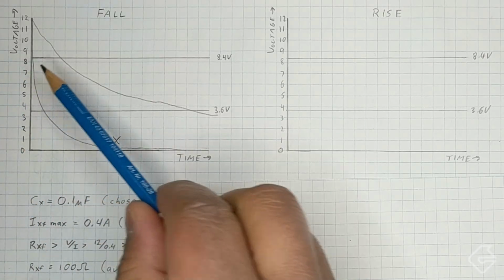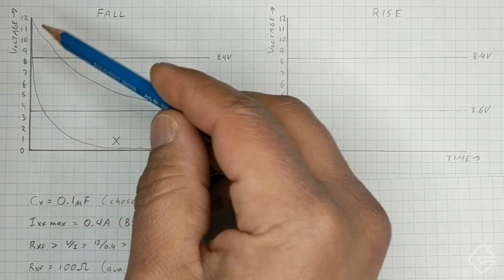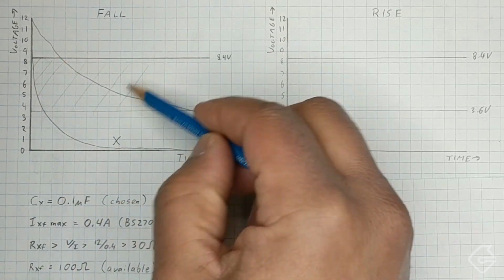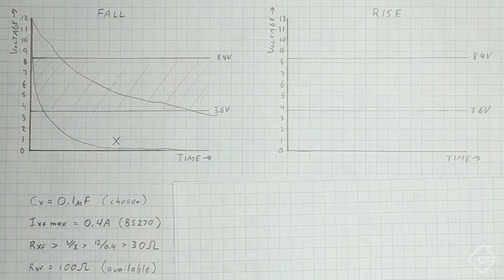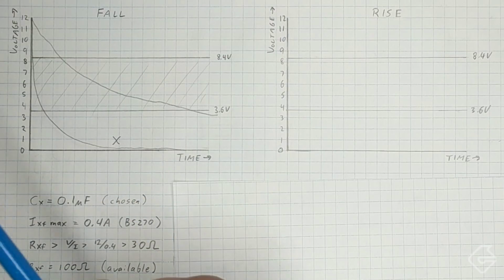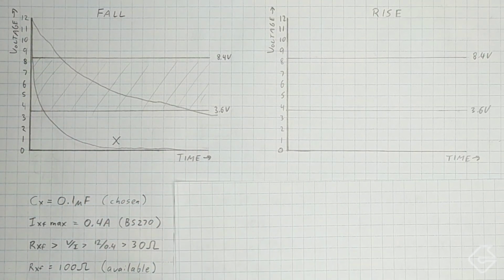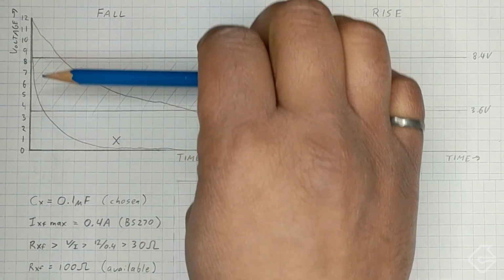And so this area in between, I'm going to call the danger zone. We do not want to linger in this zone, because in this zone, the electronics can't tell whether it's a 0 or a 1. And that's why the answer is unknown. So what was happening in the circuit was the X bouncer and the Y bouncer were changing roles within the danger zone.